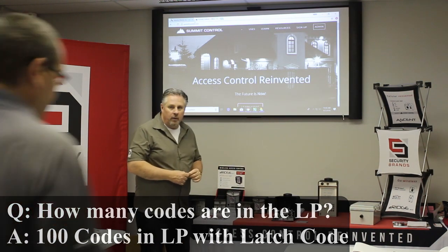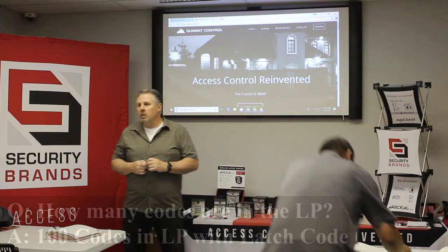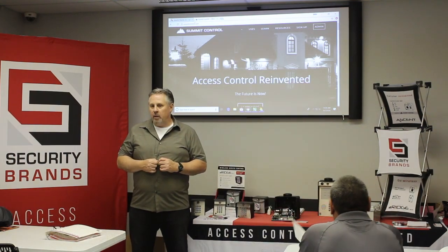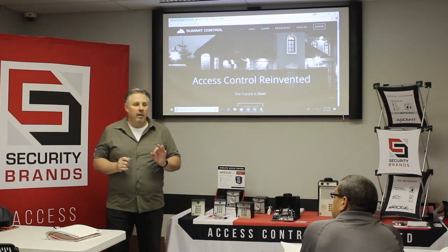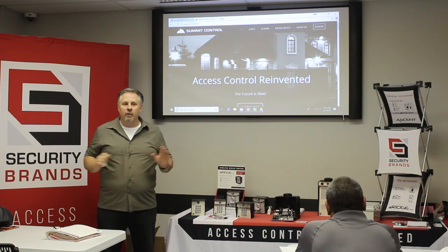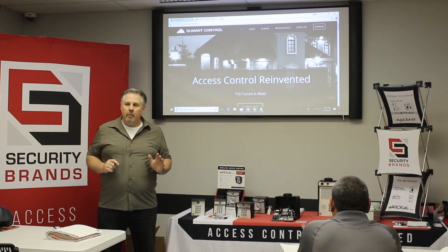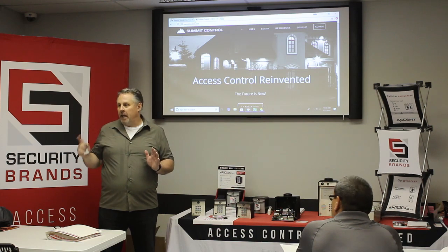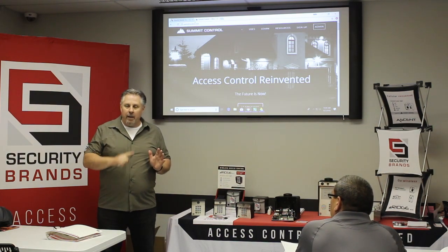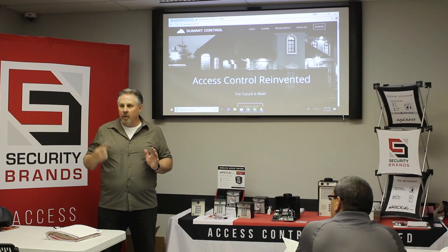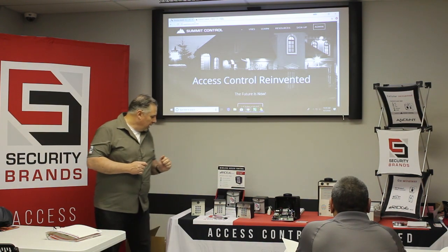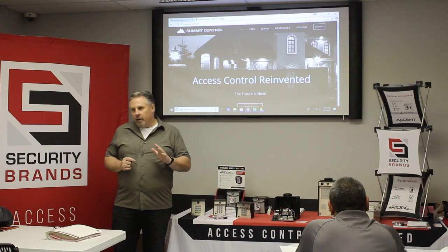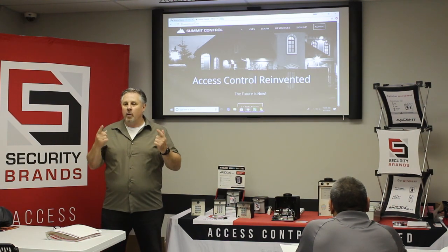So the old DKLP was less than 22 microamps of power at rest. So a microamp is 1,000th of a milliamp, which was virtually not even on. But a lot of people wanted us to provide a latch code with it. So when we added a latch code to it, it brought it up to a milliamp. So a lot of you may be familiar with a DKLP at 22 microamps. So we did change it in the last year. The way the power supply and the firmware all work together is what brought that up.